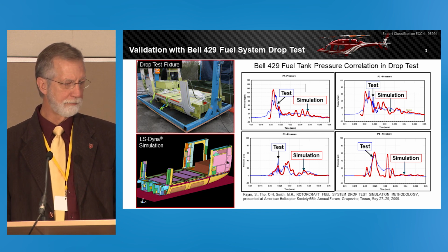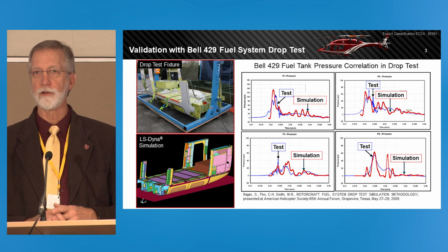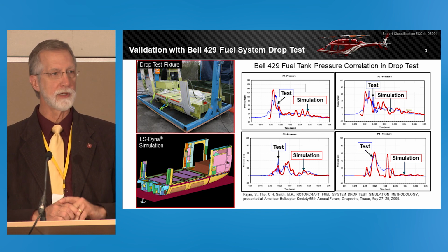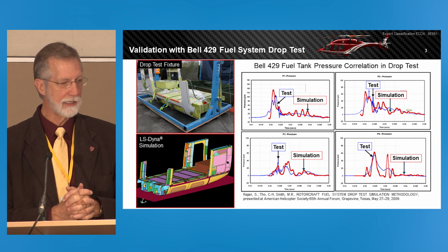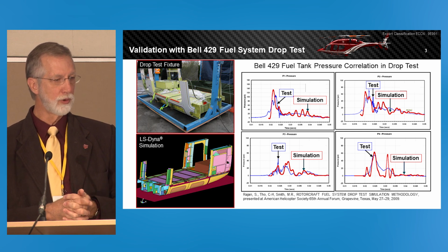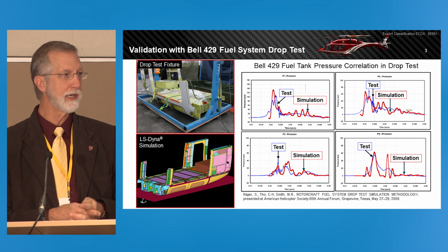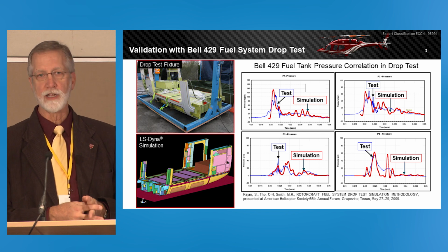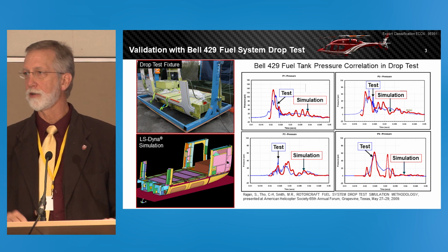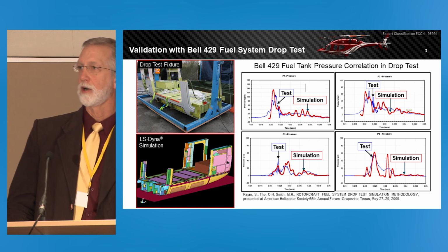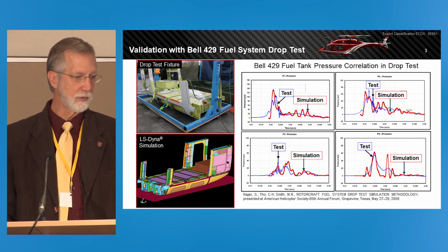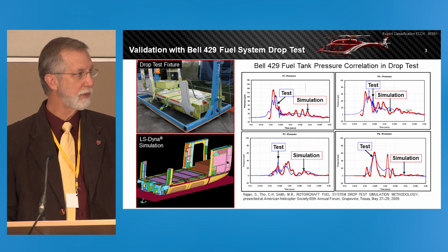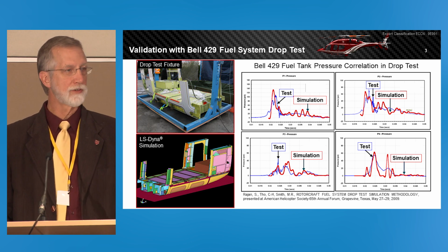We put pressure transducers in there and stretched accelerometers over that. The paper documents all of them, but these are just four of them at the end. The test was the blue and the simulation is the red. But the overall impulse energy, the integrated area under the curve, has a good agreement, as well as the peak loads and peak pressures we use for sizing.